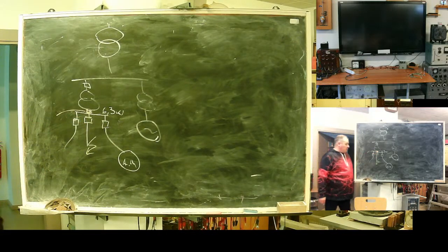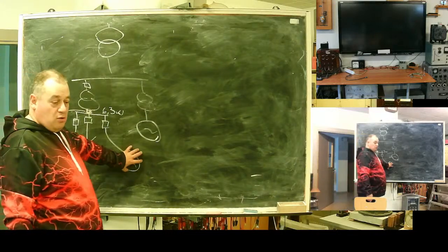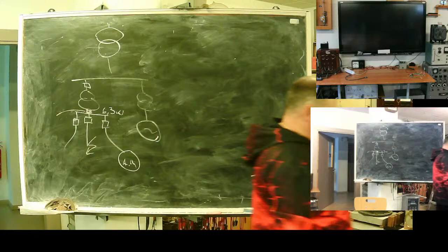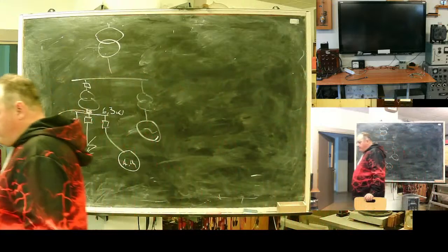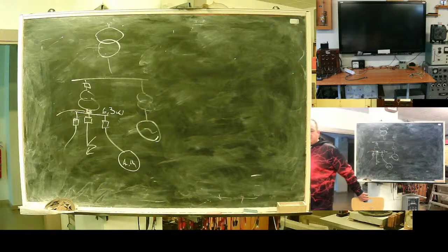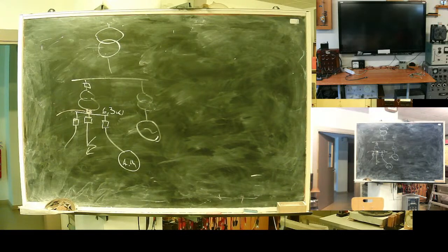And here will be a problem. High current of main pumps, if you create protection like a simple flat scheme, makes it insensitive. What to do? The idea, the solution to this problem, is the creation of two protection sets. One set operates on three-phase fault, and it's typical.